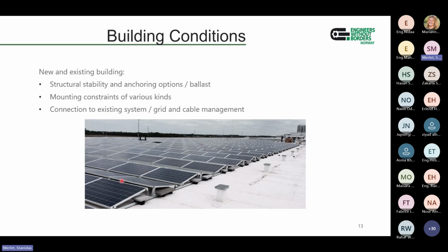But if they're portrait mounted, or vertically, another way of saying it, then the shading would be on this part, for example, and then the whole 3 diodes would be shut off. So the whole module would be off in a way. Is it clear? I guess it would be better explained with another, but Michel took this part on Monday, so